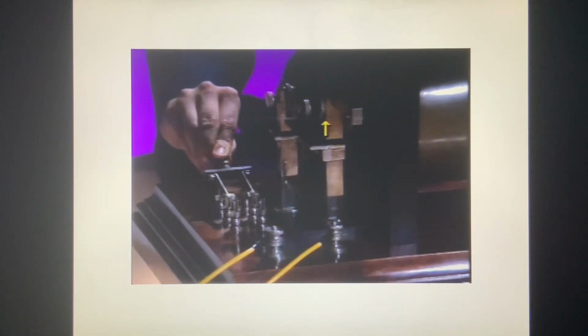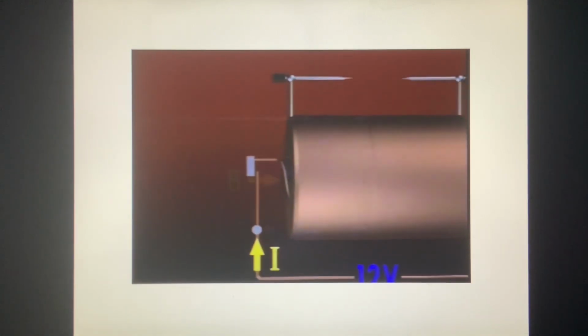This is a magnetic make and break switch. Current runs through the switch to the primary coil, and the magnetic field produced pulls the switch in towards the core, breaking the circuit. The magnetic field goes to 0, and the switch recloses, starting the cycle again. The pulsed current in the primary coil produces a high voltage pulse current in the secondary coil.